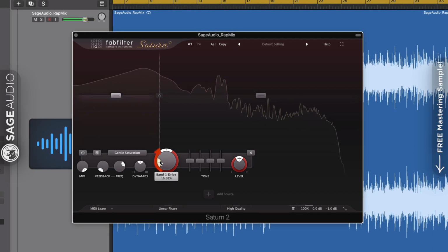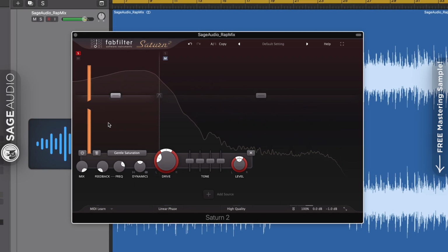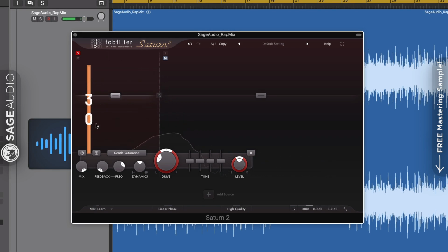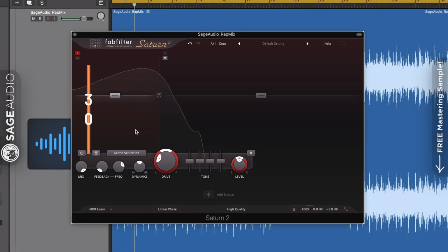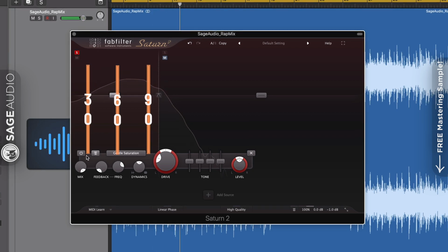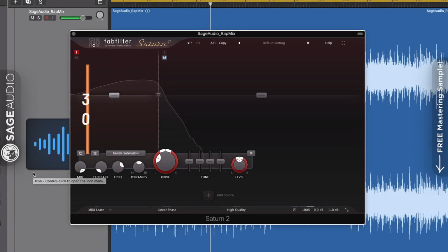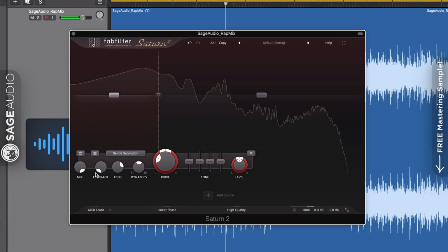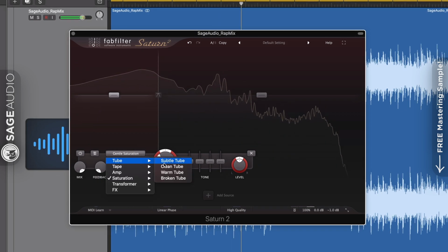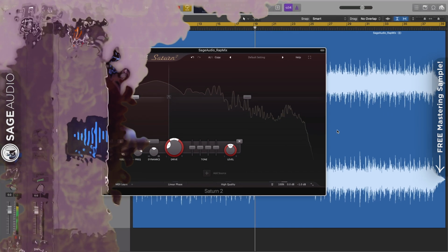By doing this, we create harmonics that make the fundamental easier to hear. So say our sub-frequency is 30 Hz, and we saturate the signal. If we get a second and third order harmonic, this means we'll also amplify 60 Hz and 90 Hz. Having these harmonics that relate to the fundamental causes a psychoacoustic effect in which our mind generates the fundamental frequency, in turn making it easier to hear. Now try different saturation types to see which one works the best, and again, if you can isolate the saturation to just the low frequencies, you should. Let's take a listen to it.